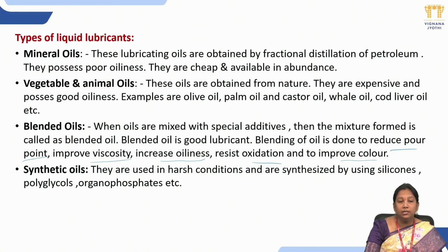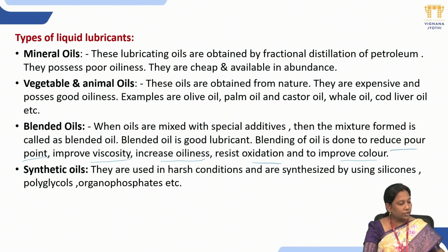And the last one is the synthetic oils. So there will be some extreme conditions, harsh conditions, where the above three types of oils cannot be applicable. So in those cases, synthetic oils are used, and these are synthesized generally by using silicones, polyglycols, organic phosphates, etc.